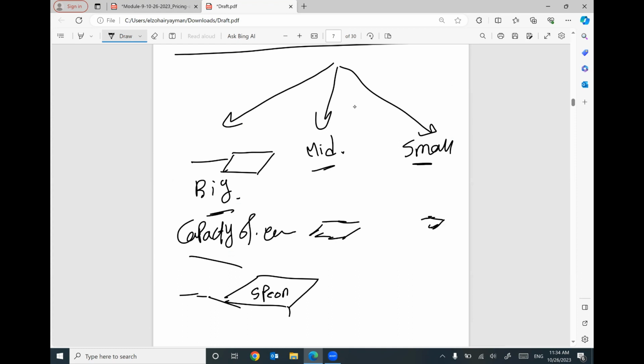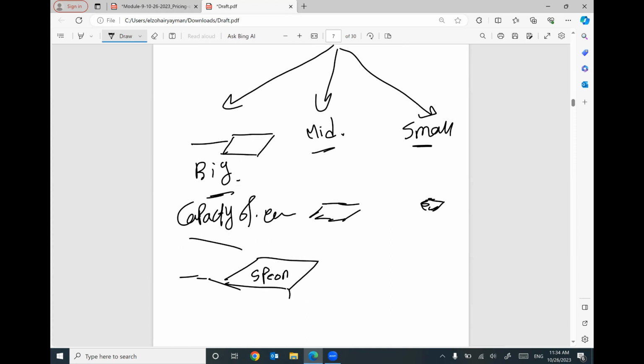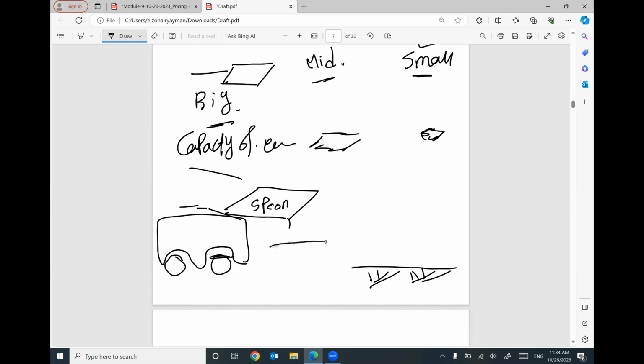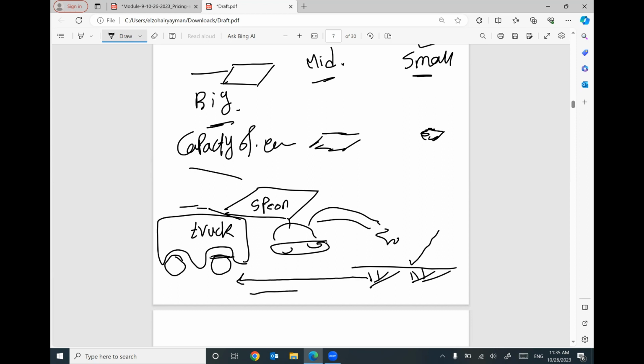The smallest one will have the smallest capacity to excavate. This is the capacity. And also, you need to understand you are excavating soil here. What is the nearest point your truck can stand? Because your excavator will travel from the position of excavation to the truck to put the excavated soil. So what is the time to excavate and to go to the truck and return back?